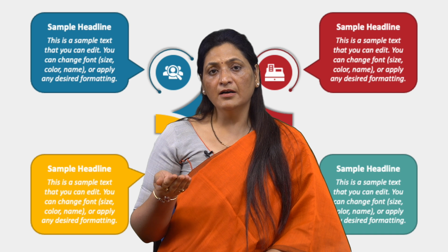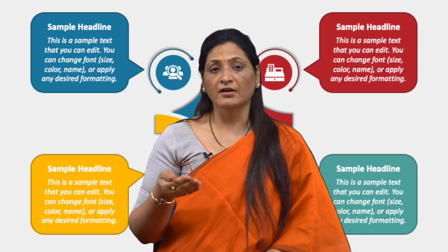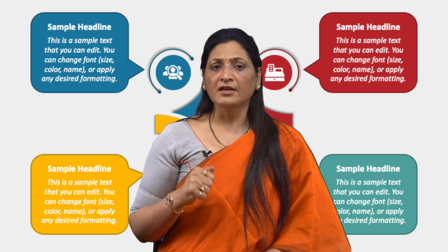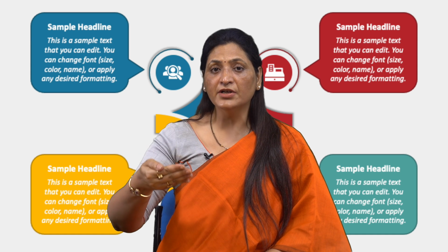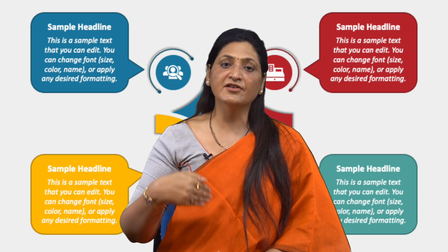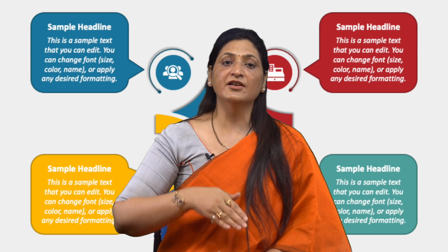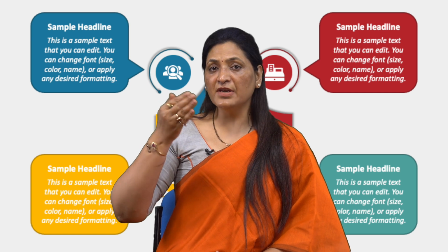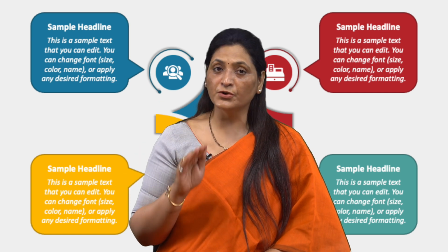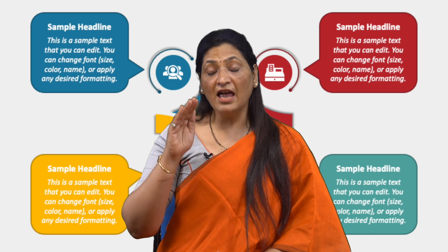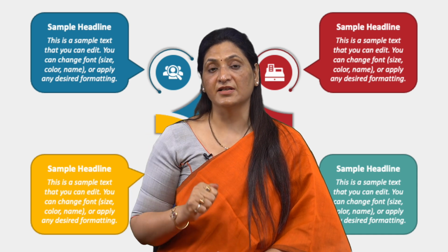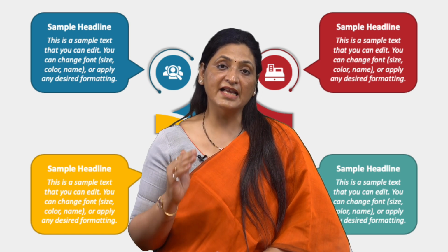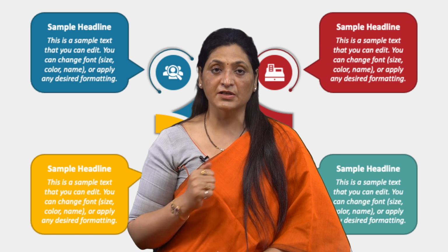Now, during deceleration, the dynamic torque, which is J d by dt of omega m, has a negative sign. Therefore, it assists the motor developed torque T and maintains the drive motion by extracting energy from the stored kinetic energy. So, the speed of the system is not determined by the motor only, but it is also heavily dependent on the load characteristics. Hence, the characteristics of the load cannot be ignored when we are designing an effective electric drive system.